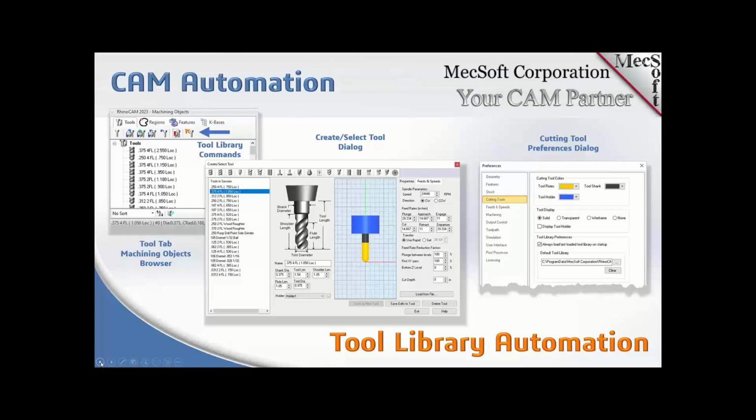Basically what that does is save any geometry, any layers that you want to have displayed. A lot of users actually have a base file that has their spoilboard or a fixture that you always have on your spoilboard. They work that into their template file, so every time they create a new project, it's there. So that's just one level of automation you can do with RhinoCAM or VisualCAD. Okay, with that said, we're going to be going a little bit slower than we normally do and see if we can get all this stuff in so that we can get this cohesive workflow through here.